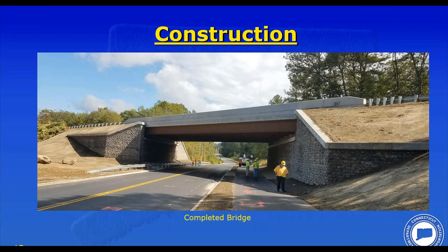Versus 7 months. Was that 10? I think 7 months. Versus the other project, it was 15 months. So the real difference was the previous project saved more time in construction, thereby reducing the overall project cost by reducing the construction, engineering, and inspection cost. So here the ABC project wasn't that much faster than conventional construction, which is why we could not overcome the additional ABC cost with savings in construction management. So that's the primary reason why this went that way.